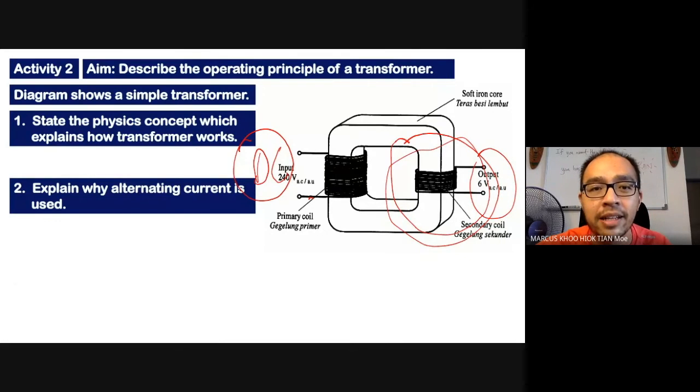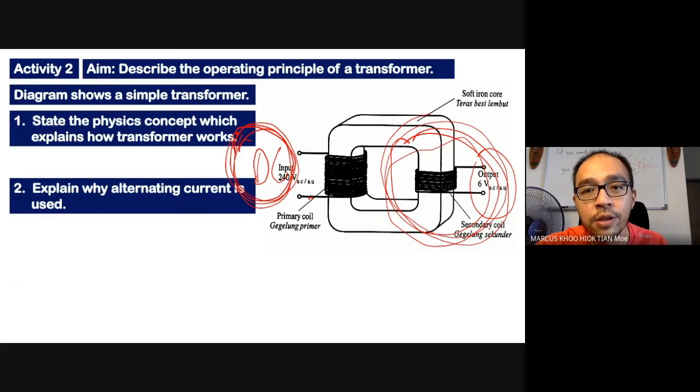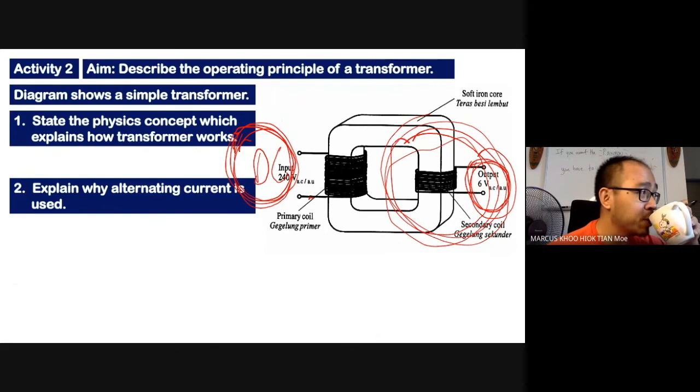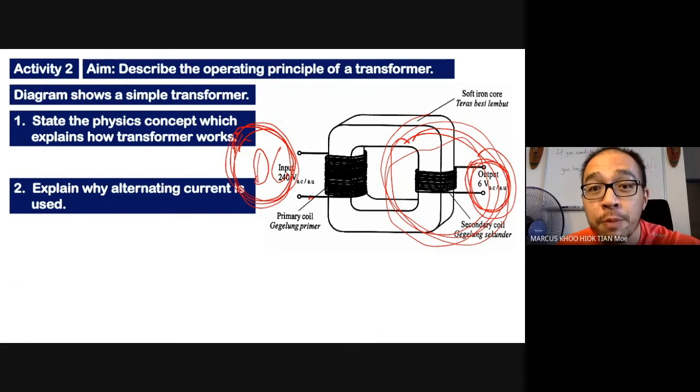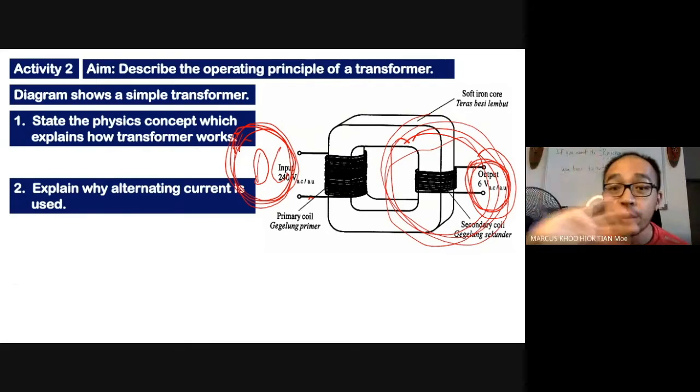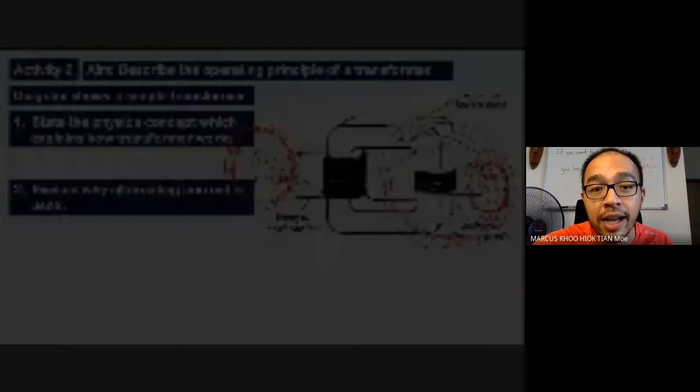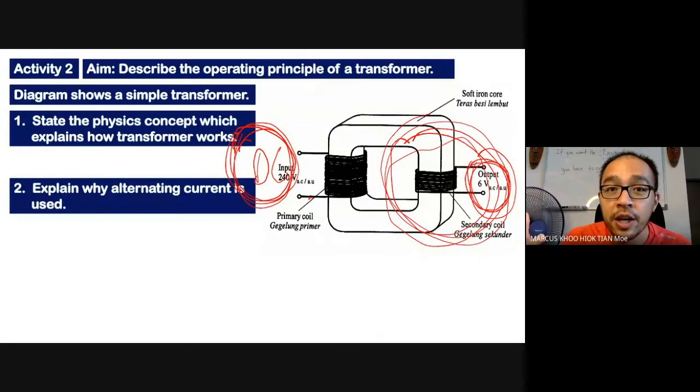Let's say I provide direct current, just a battery here, but I want to make sure that this transformer is functioning. What should I do to this side in order to get this output voltage over here? How would you move the coil, Mordecai? Yeah, you probably have to use an external force. You probably have to have somebody hold the coil and move it like this, so that the magnetic field from the direct current will always cut the coil, which is kind of silly, right?